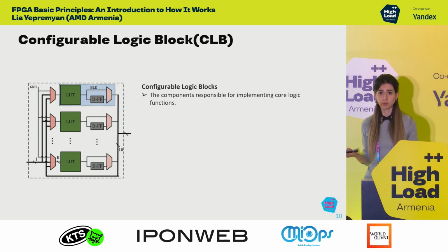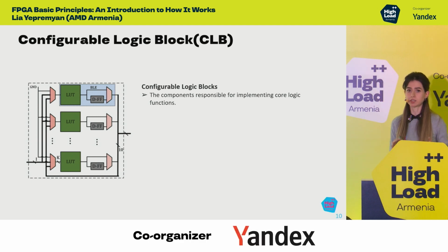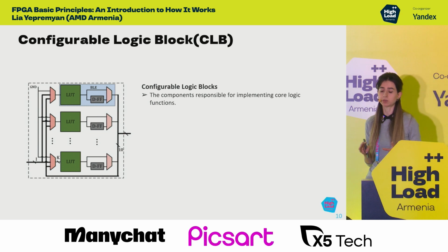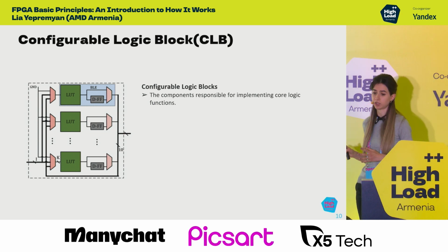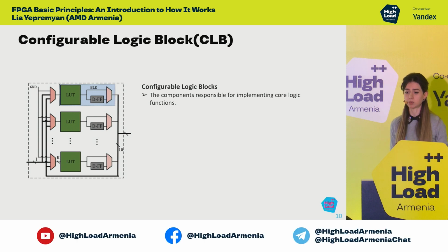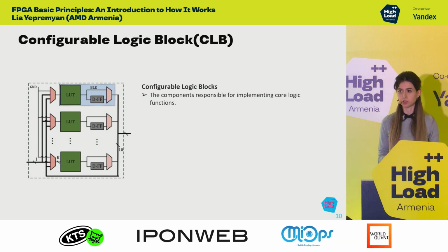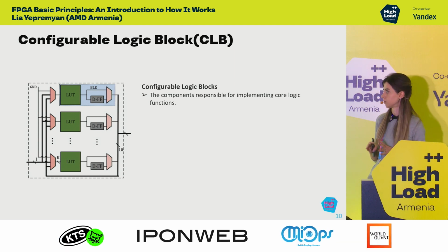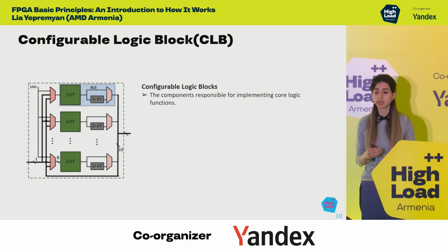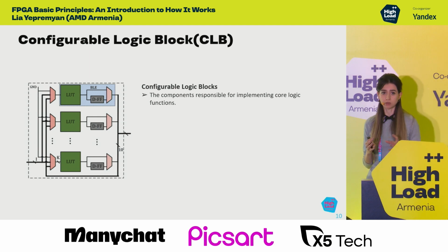From a superficial point of view, we can imagine that the FPGA consists of AND gates, OR gates, or other elements, but actually they don't exist physically in the FPGA. Logic blocks are configured so that they behave like this. To achieve this, we use lookup tables. Lookup tables on the FPGA hold truth tables, which are loaded when our FPGA is powered up. We can even imagine that our lookup table is a piece of RAM, which is loaded whenever we power up our chip.